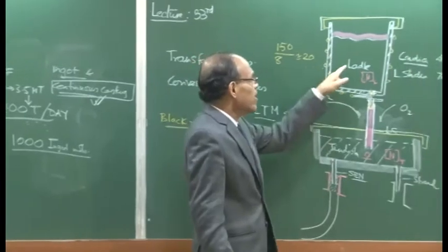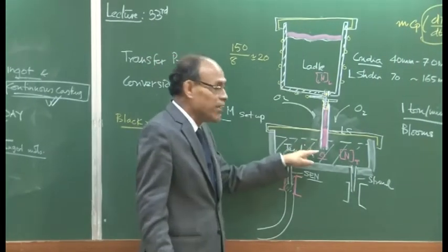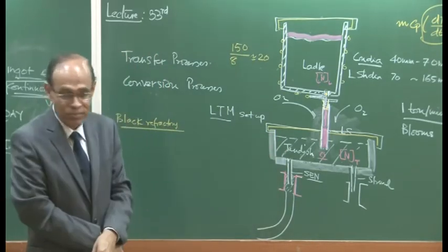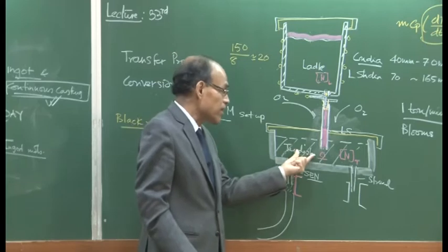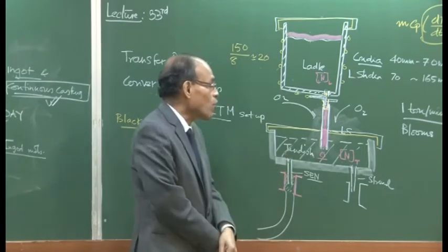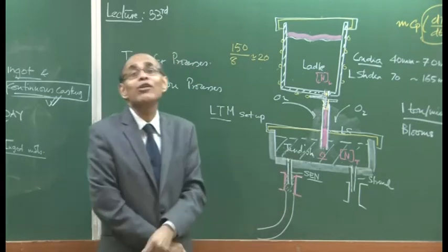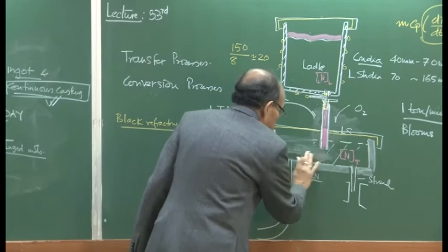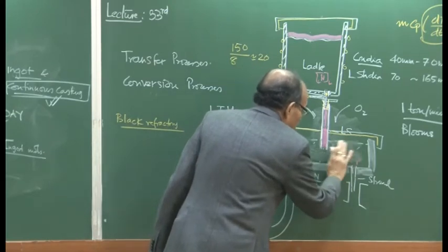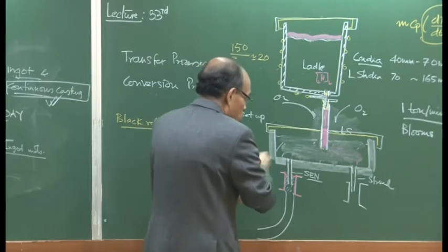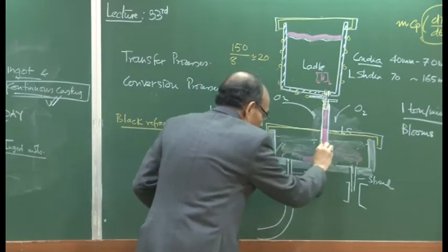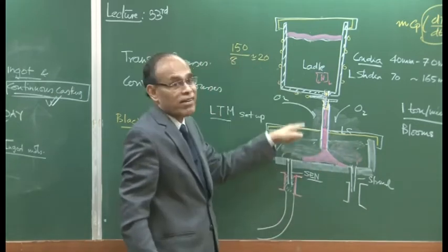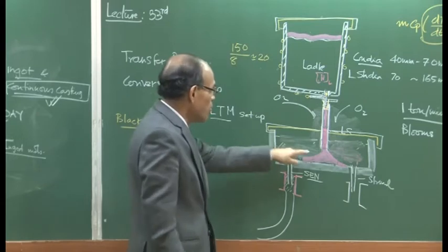So when a ladle is brought to the turret, the ladle is opened into a tundish. The tundish is empty, but it is hot, and if you have not taken care, it is filled with atmospheric air. So in an initial tundish which is empty, when molten metal is discharged and starts to flow, it is creating a scenario like an open air casting process, because it is filled with atmospheric air.